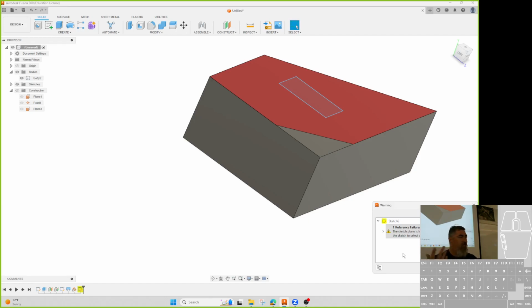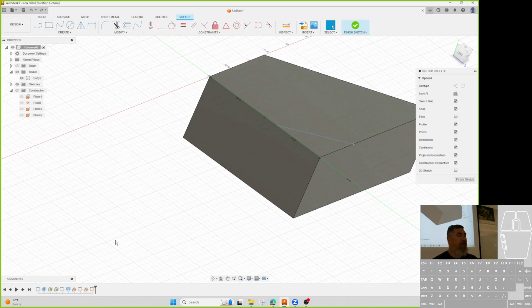I do that. When you make reference things based on a sketch, it doesn't turn off automatically. So if you are gonna use a sketch to make reference geometry and things, you have to manually turn it off. You don't want to leave that sketch turned on when you move on to the next thing. Okay, does that make sense? And so for me, the benefit of using reference geometry is I don't have to worry about that. It's not an extra sketch in my timeline that's muddying things up.